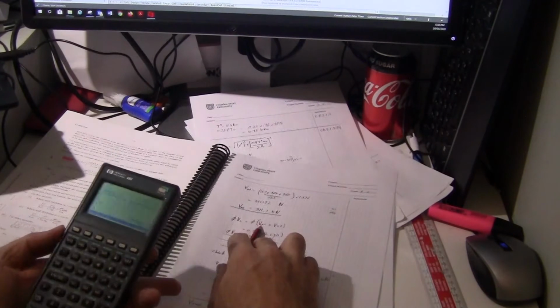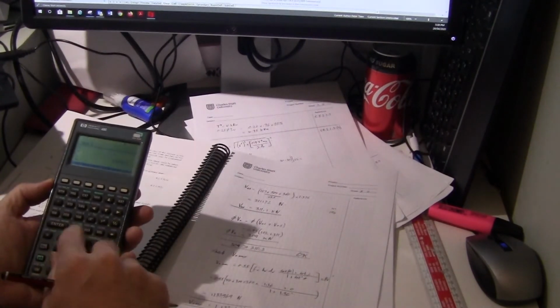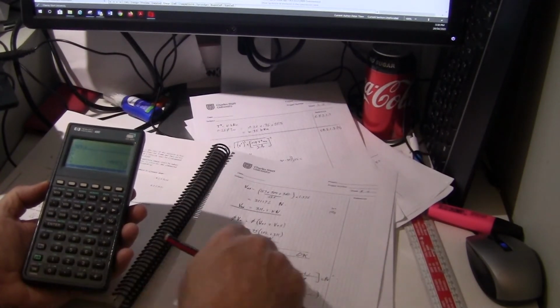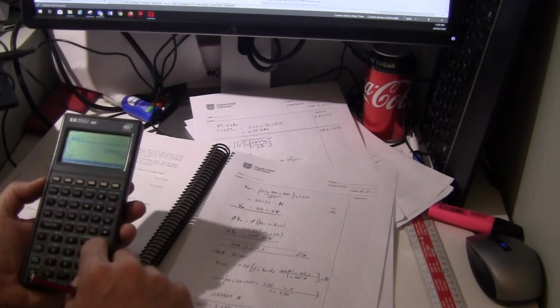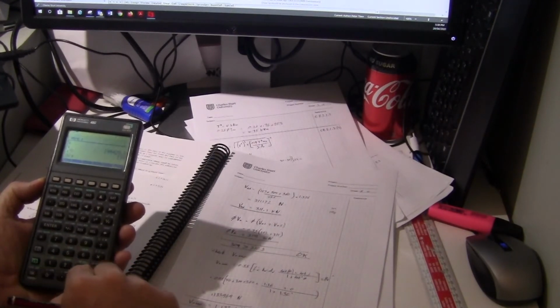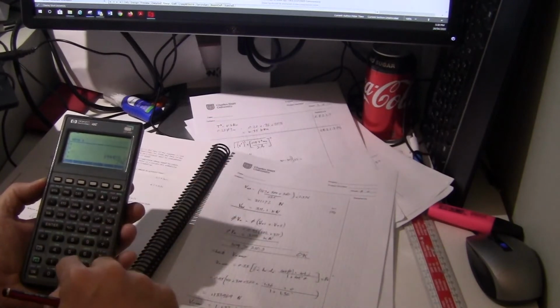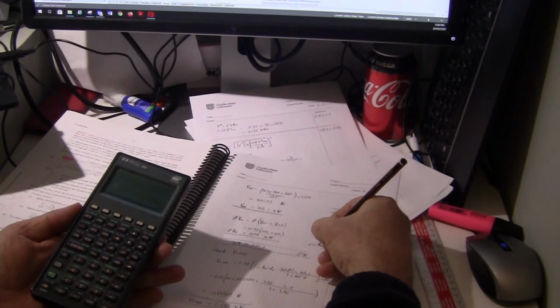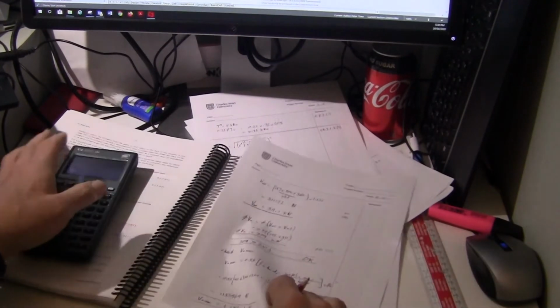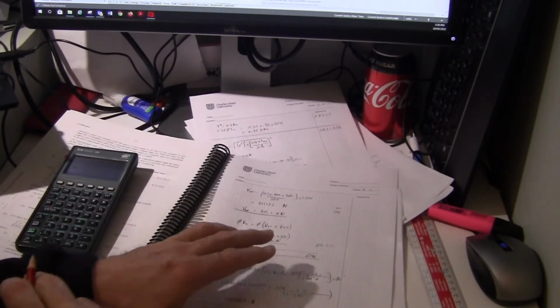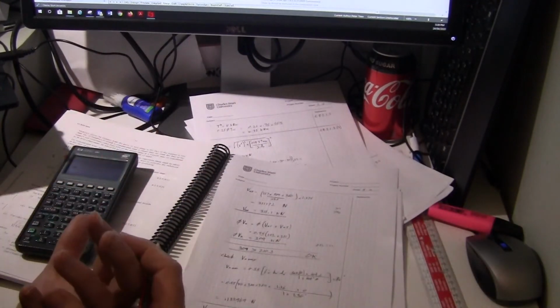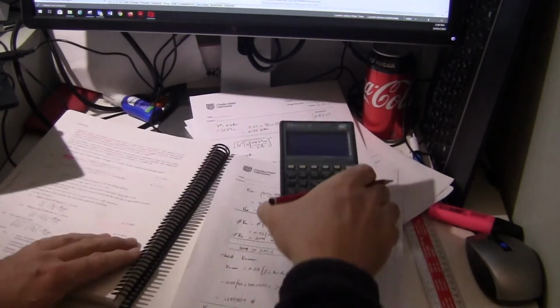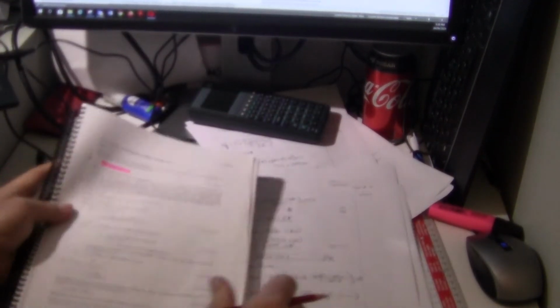Okay, so our VUC plus VUS would be 194 plus the 102, which is 296 times 0.75. We would have a phi VU of 222. And that would be a lot closer to our 210. So that would be a more efficient design. However, because we have torsion, we have some more restrictions on these rings. And this is why that 125 came in.